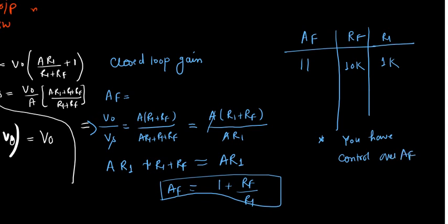Correct? Now the value of closed loop gain is not of the order of 10 to the power 5. It was 10 to the power 5 for 741C, right? That was causing trouble, that we cannot amplify very small signals. But now you can, because our gain is 10, 12, 20, whatever we want. If you want a signal 10 times larger, we can do that by selecting the values of R1 and RF. Correct? But now the question is, can we choose a signal of any frequency?